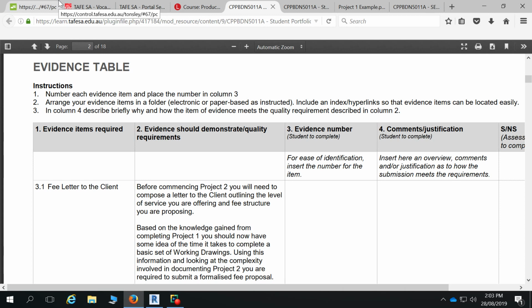Top and bottom level. And obviously there were floor joists involved which had a size, you know, they were close to 400. And when you added all that height up, it was much greater than what council said they wanted as a maximum height of building. So we had to start squashing things in. There were lots of things with millimetre tolerances in this build, to the point where the builder was ringing us up and saying, can I go up by another 5 mil for this? I can't fit this in, those sorts of things.